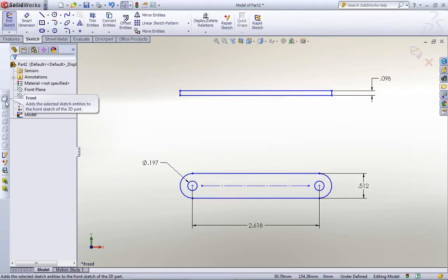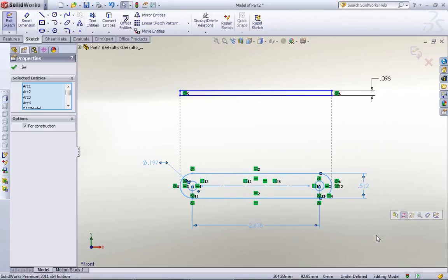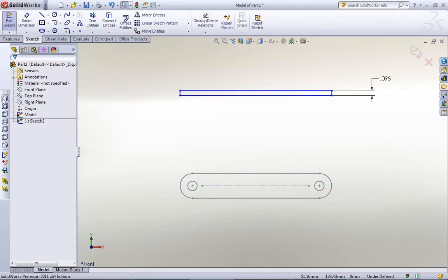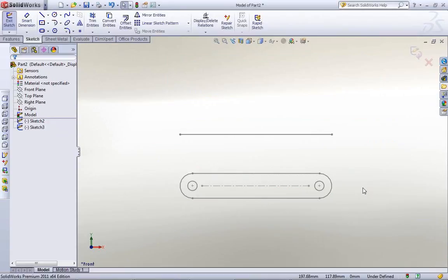And what you do is you basically just pick portions of this to make the front, make the top, make the left views. So I'm going to just do a box select, a very familiar command there, and make that the front view. And you can see it sort of grays it out. Okay, now you've defined that. Now that I've defined that, I can say make that the top view. And you see it sort of orients it.